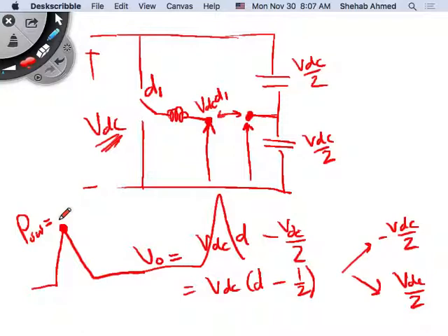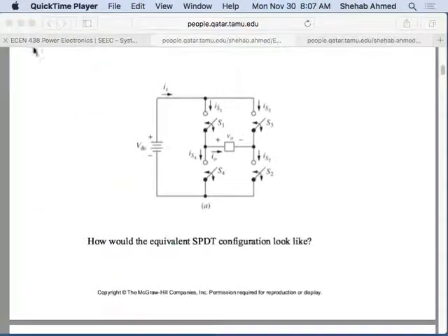So the cost that you save on 2 switches, you may have to invest in a heatsink, right? And if you want to make it small, definitely go for something without a heatsink. So maybe in that case, definitely go towards a full bridge, right? It depends, again, on how you optimize, what the load's requirements are, how the system is optimized, what the ambient temperature is, etc., to be able to choose. But these are 2 topologies that we can utilize to produce AC voltage here.